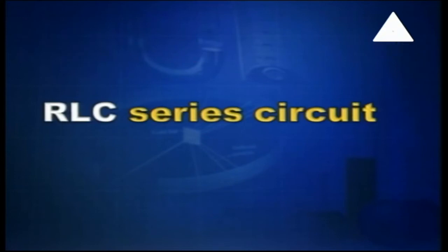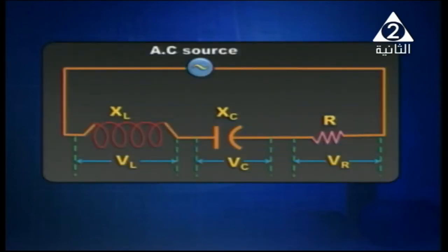And finally, what if the circuit contains RLC? So, an RLC series circuit. R refers to the ohmic resistor, L the inductor, C the capacitor. They are all connected in series to an AC supply. Once again, the voltage across the inductor is denoted by VL, that across the capacitor is denoted by VC, and that across the ohmic resistor is denoted by VR. VL is the product of I and XL. VC is the product of I and XC. VR is the product of I and R.